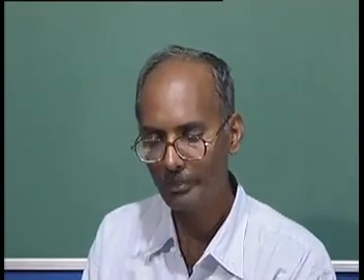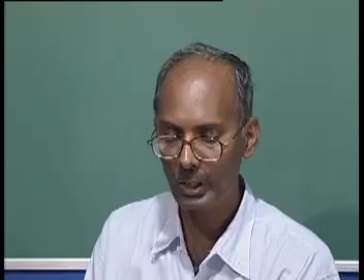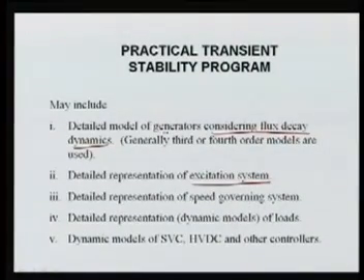So in the detailed and practical transient stability program, we have to model the generators in detail, the excitation system, the speed governing system as well, and we also have to go for a detailed representation of the loads.